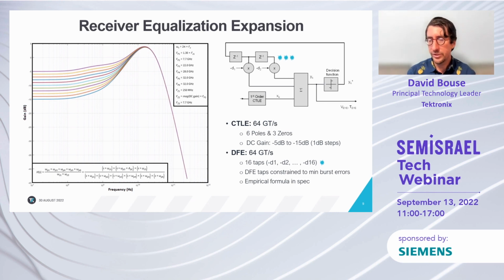We have the traditional correction techniques, CRC, replay, but we also have a low latency FEC, or FEC, people call it now as well. And because of that, we're allowed to focus our BER at E⁻⁶ instead of E⁻12, which we've done historically, which is one of the key components that allowed us to get to PAM4 signaling.